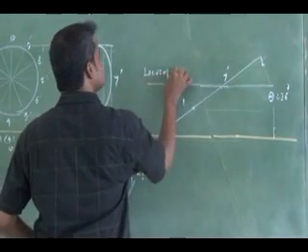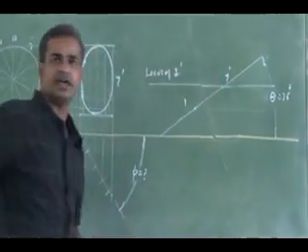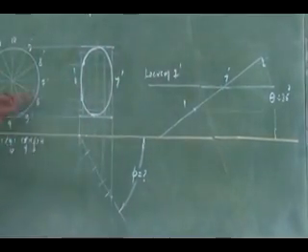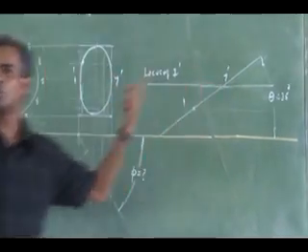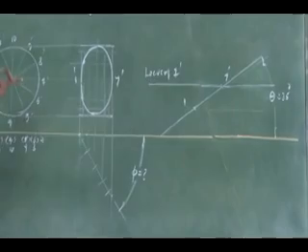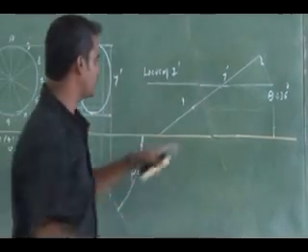Locus of 7 dash. I have 7 dash already. Now what is the true length? This is nothing but the top view length of this diameter 1/7. The true length of the diameter 1/7 is 60. That 60 I can measure in my compass.